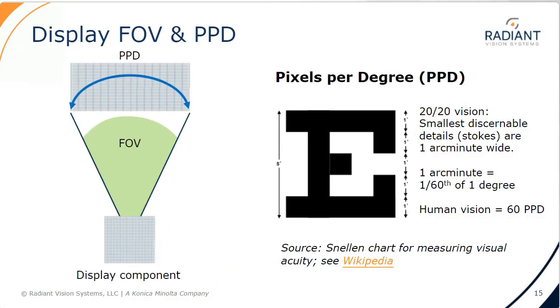So pixels per degree, PPD, is influenced by field of view versus the XR display resolution. PPD is the display resolution visualized over the angular field of view of the display. Higher PPD increases the amount of visual detail, which typically is a goal of XR optical design, to create an immersive image. The in-display measurement, the imaging resolution applied to capture the display field of view, should exceed the resolution of the XR display itself, and hopefully greatly exceed.